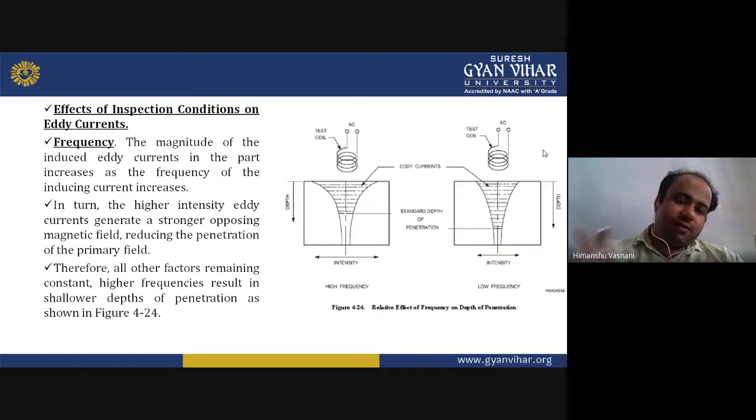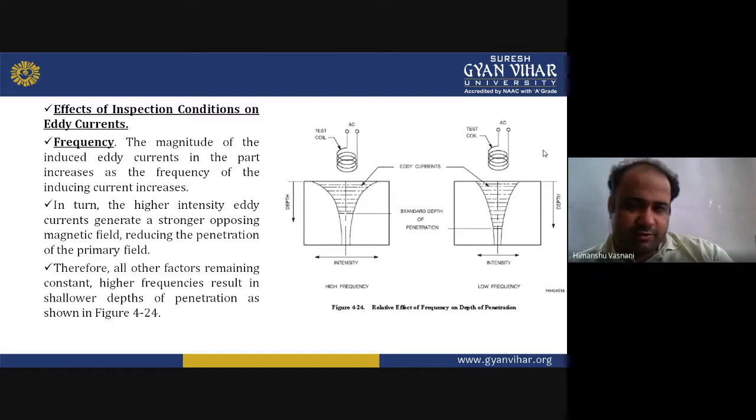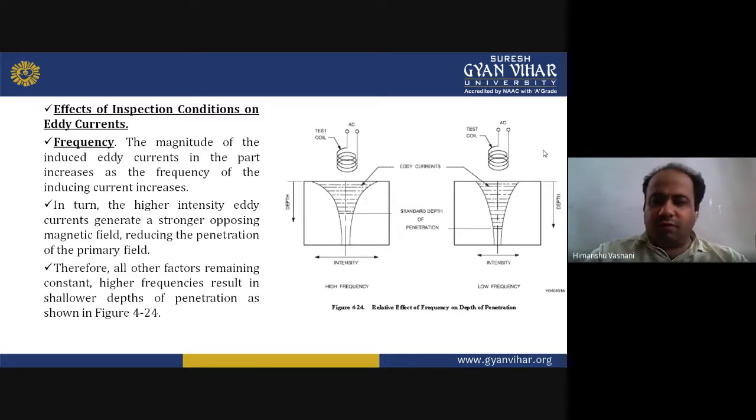You can see in the first diagram, it is clearly the statement holds true that when you have higher frequencies, this results in shallow depth of penetration. And if you have low frequencies, they will result in deeper depth of penetration. You can say verified from the diagram also. So the magnitude of the induced eddy current in the part increases as the frequency of the inducing current also increases. So we have to be careful with that.